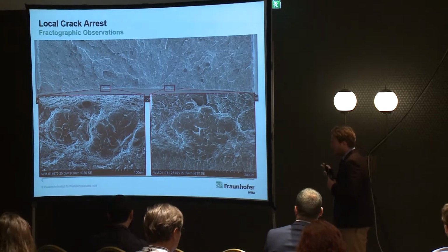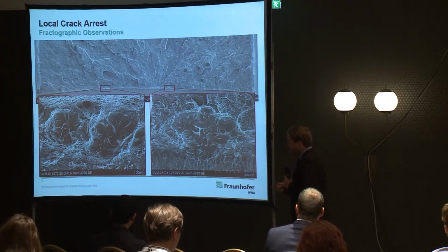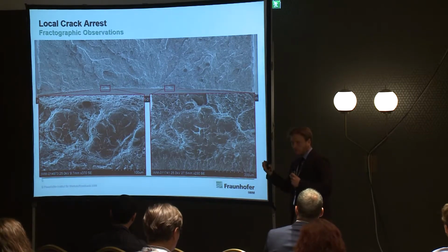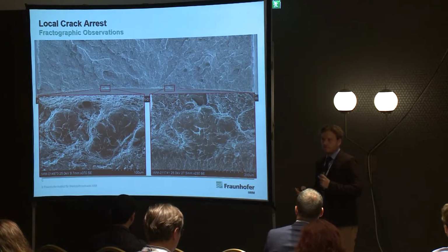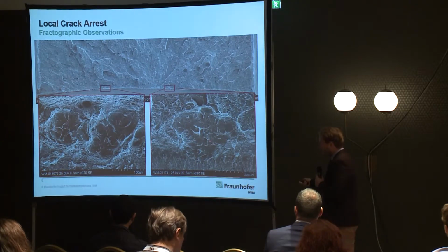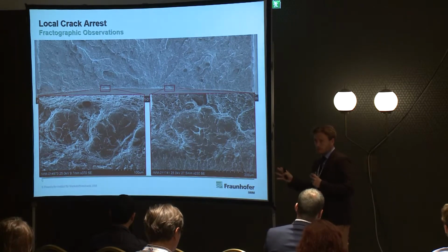And they're clear evidence that sometime during the load history, we don't know when, cleavage is initiated. We can see that in the facets right here, and they have arrested after several microns, maybe 100 microns of crack propagation. We see these diameters of about 50 to several hundred microns in diameter, but they're relatively local incidences. They don't have to do with macroscopic crack arrest or anything like that.